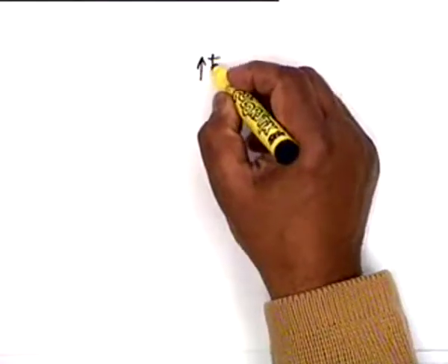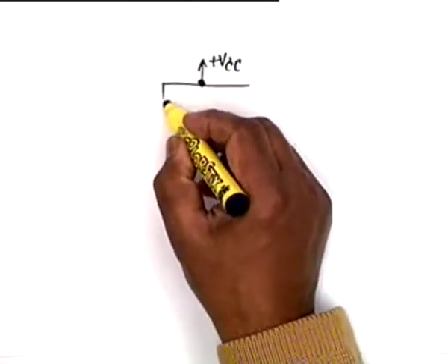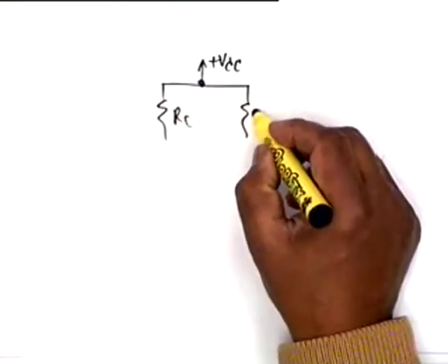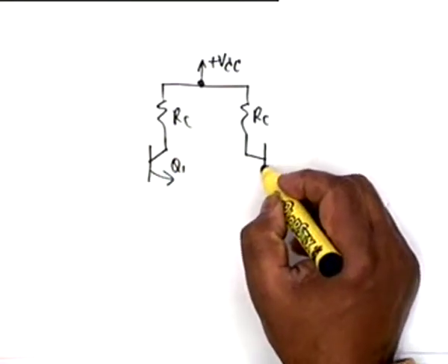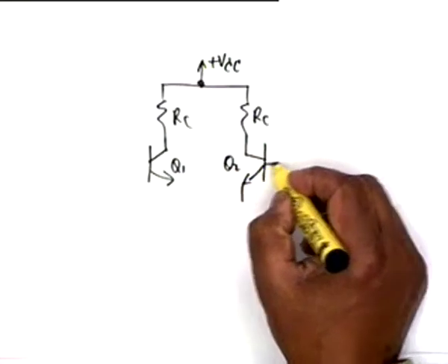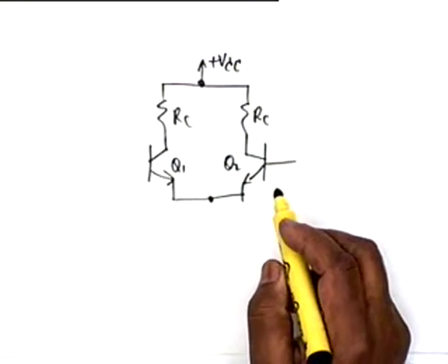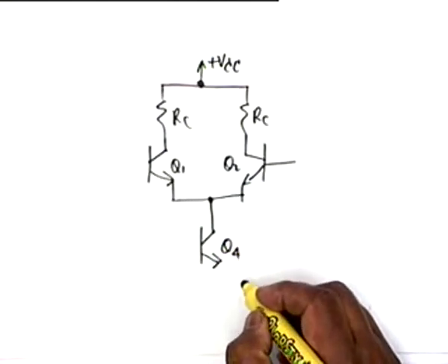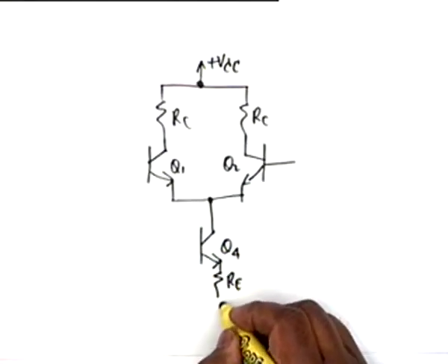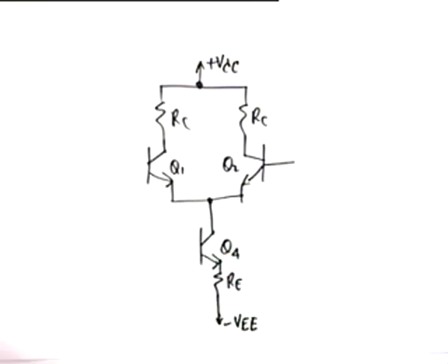All right. So our circuit, how RE is used, is like this. VCC, we'll draw it quickly. R sub C, then we have the two main transistors Q1 and Q2. These are connected together. This is supposed to go to REE. Instead, what we do is we take it to a transistor, let's say Q4, RE. This goes to minus VEE. This is the main transistor of the current mirror, and this is that Widlar resistance RE.